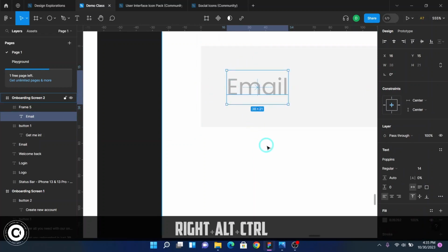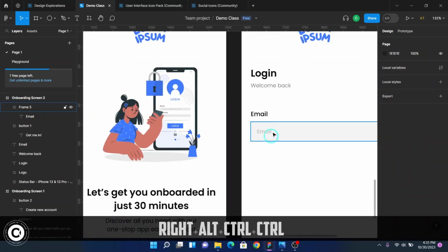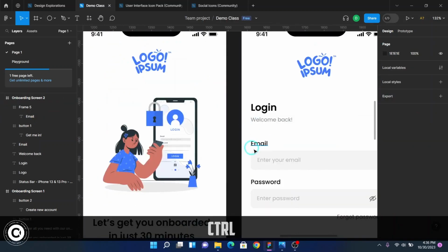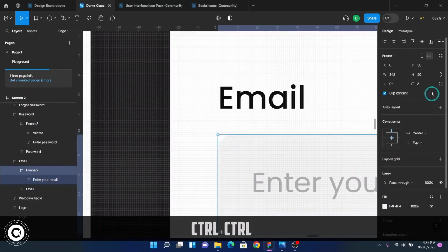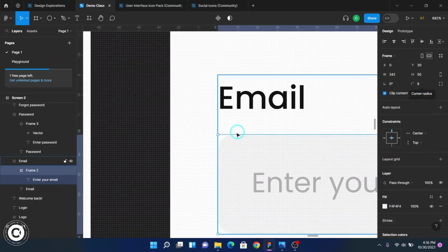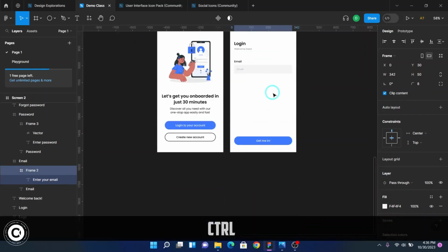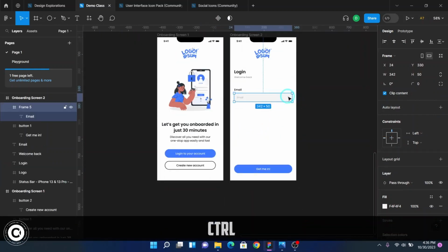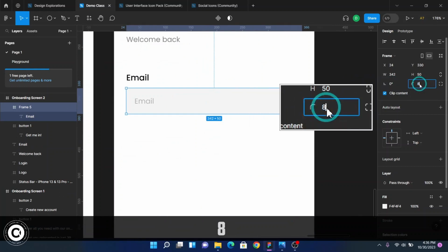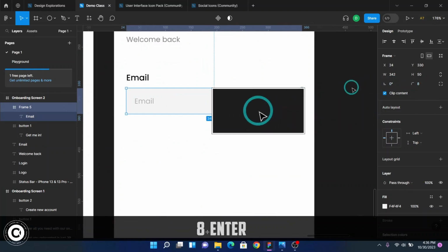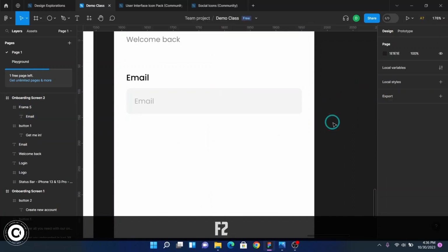Yeah, 16 that way. Okay, so now it's a bit rounded. You look at the edges at the top here, you can see it's a bit rounded. So for the corner radius, I use 8 for that. Right now it's on default value, which is 0. So when I click on 8, it becomes rounded. Good. So nothing serious, just makes our design look better.